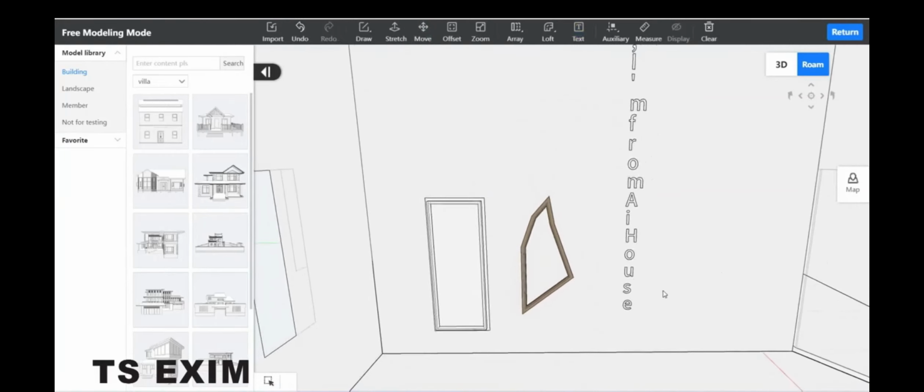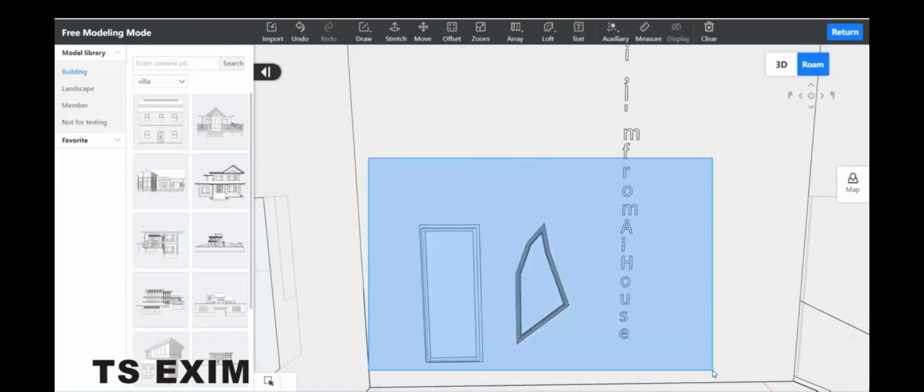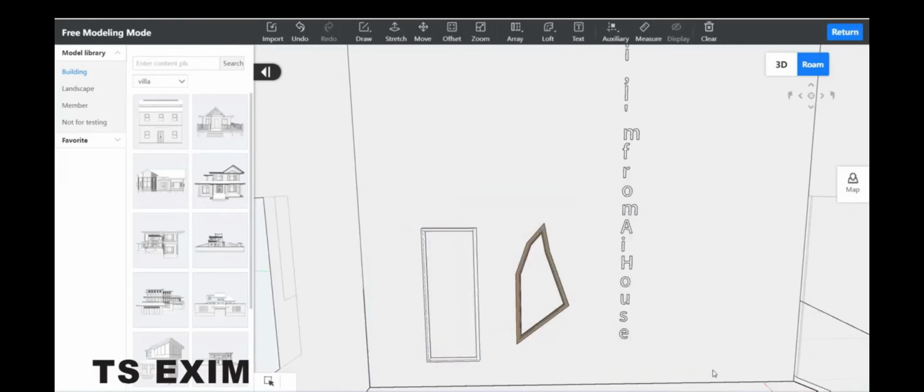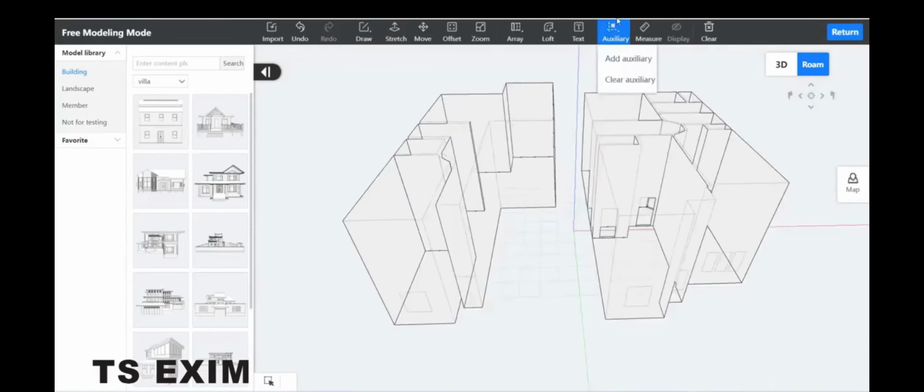So we have done all the buttons. Now you can try deleting everything. For loft you cannot highlight and delete. You need to select the loft and delete it one by one. Only for loft. Other than that, you can highlight and press the delete button.